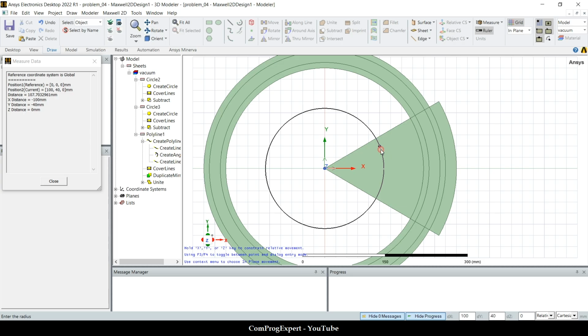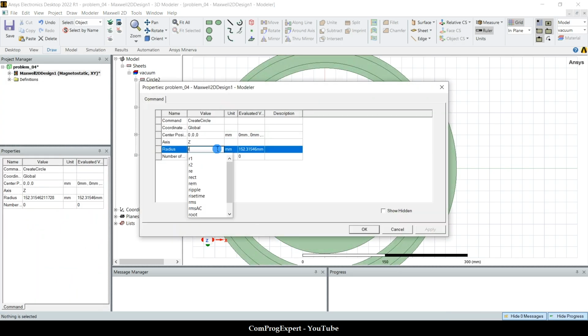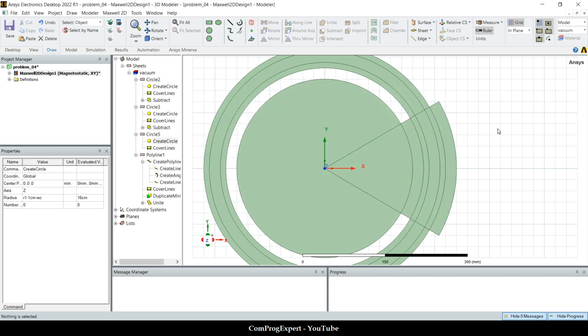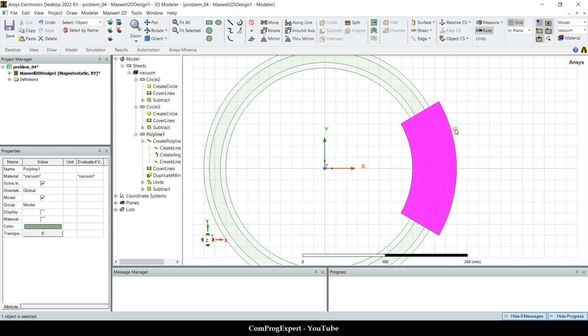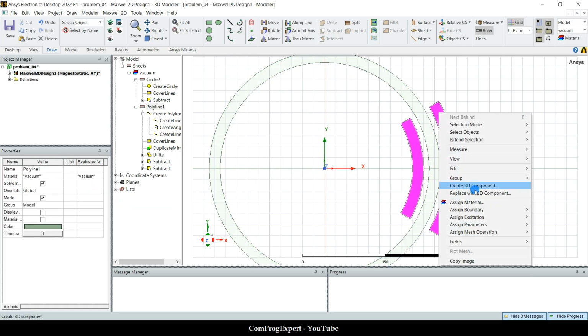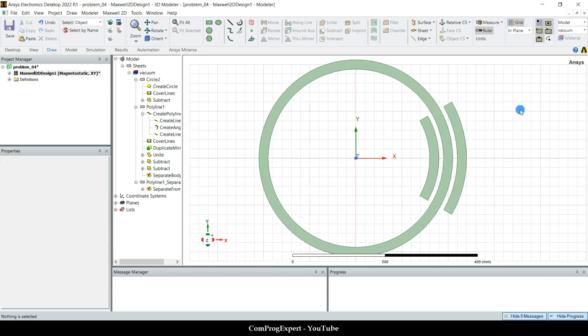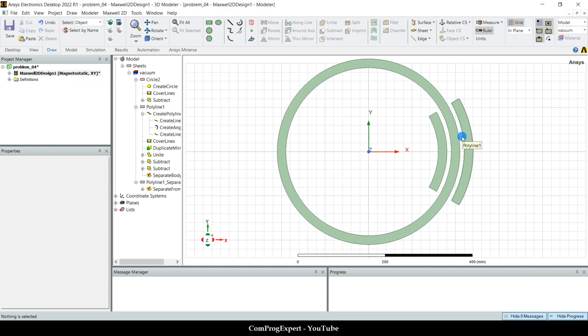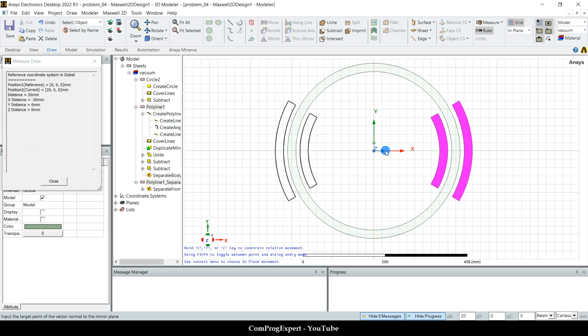Finally, we can subtract it from another circle. So let's draw another circle. Set the radius equal to R1 minus 1 centimeter minus width of the coil. Select this object, subtract this one, subtract, and select this object, edit, Boolean, separate bodies, right? So we can generate this geometry and we can select these two objects, consider the same geometries for the coil 1 also, right?